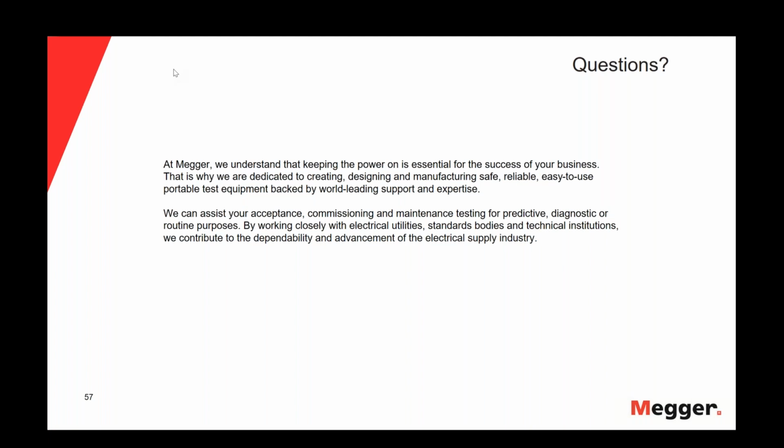And here we're not talking about monitored withstand with Tan Delta, because that's a useless test on new cables. We're talking PD. So if you talk to, let's say, Europeans, Middle Eastern, all of these areas, the monitored withstand is the VLF test. It's the over voltage test, plus monitoring the PD during commissioning. So that is very common, and it's now the latest, hottest trend. And the standards committees are now slowly getting in motion. They need a little bit of time to gain inertia. You know how this is.